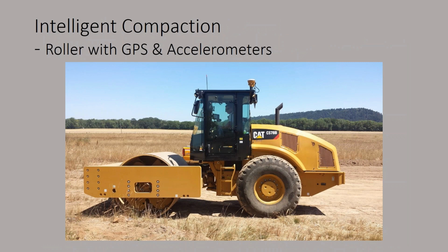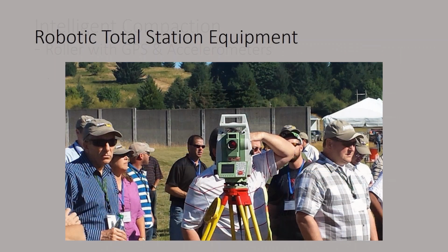There's also some readings they can take. Right now, I don't think that's perfected as far as the stiffness of the soil or stiffness of the asphalt if you're paving, because that's all dependent on temperature of the asphalt and other things. And so you've got to collect an awful lot of data to try to correlate whether it's been compacted enough or compacted too much in the case of asphalt.